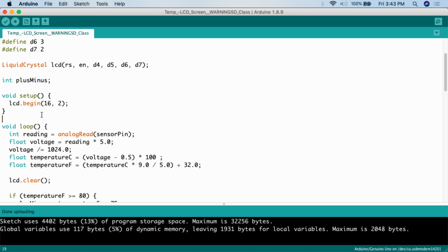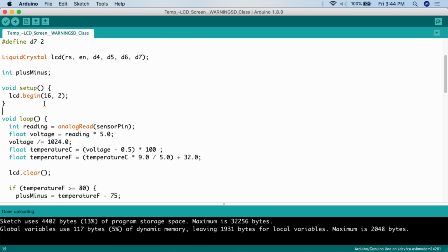The loop is going to run in order to do that. We're going to do lcd.begin, and we are going to say what kind of LCD screen we have. So it's 16 columns, so 16 characters across by 2 rows, 2 characters up and down, right? So 16 by 2, and we use this in order to do the cursor settings and all that, because you actually have to tell the code where to start typing things out, which can be a bit of a pain in the butt.